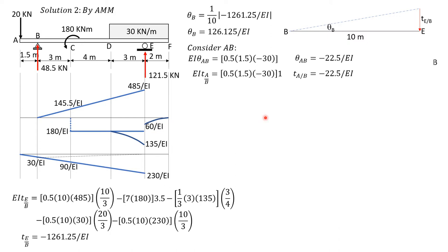So let's draw so that we can analyze theta A and delta A. If this is the line, B is on the horizontal line, and A is below, because the deviation of A relative to B is below the reference tangent at B. So let's draw the tangent at B. Remember that this is theta B, which is positive, inclined up.